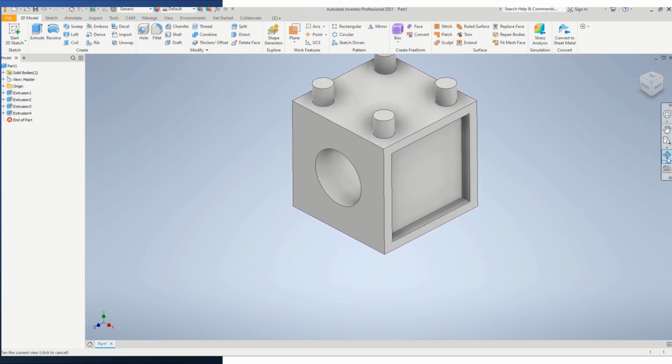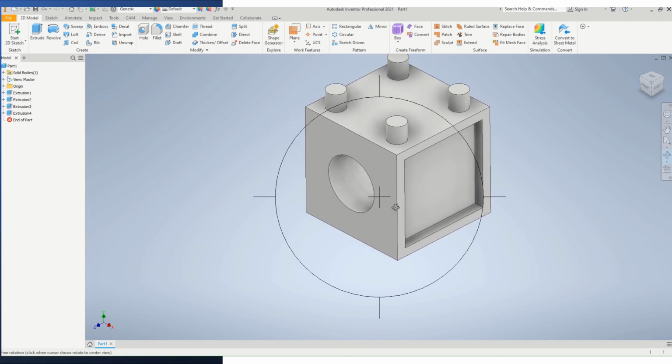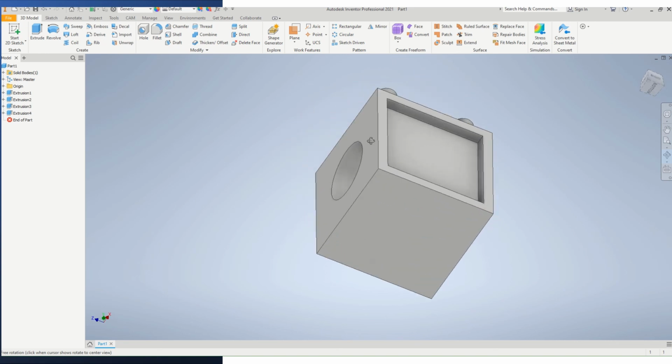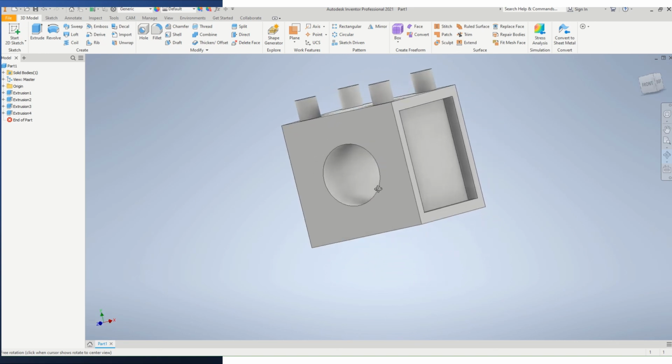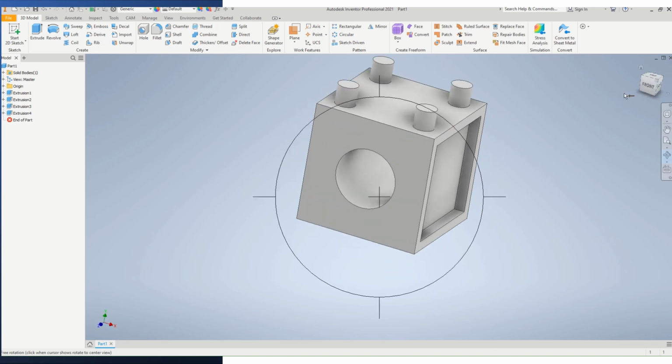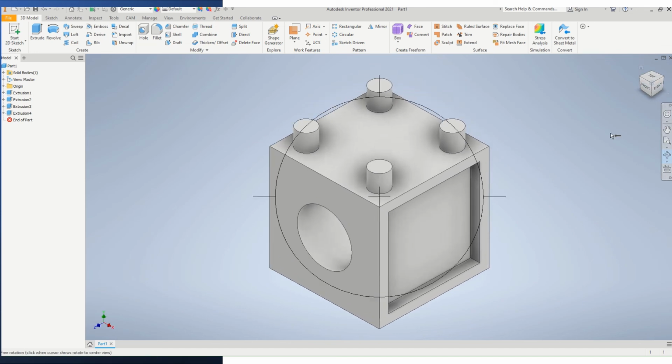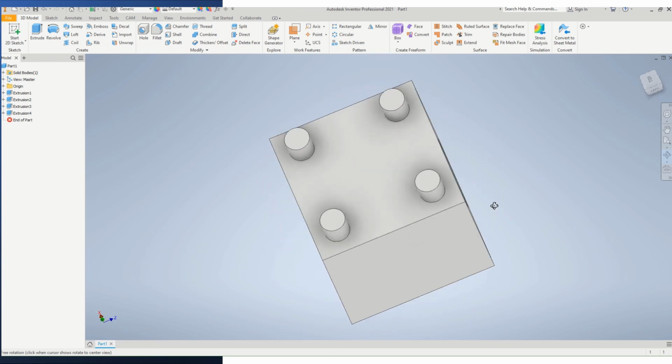And if you click this little rolly ball here and you hold down your mouse ball and you click, you're able to move it around with a little bit more finesse than if you were to toggle this cube up here. So to get it home, if you want to have a little bit more finesse, you'll use the orbit ball. So you'll click on that, you'll hold down your mouse, and now I can move this around as well.